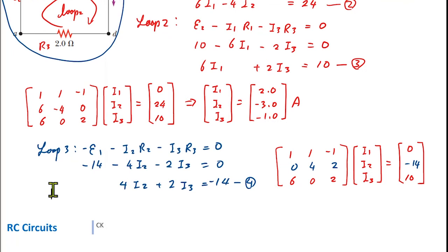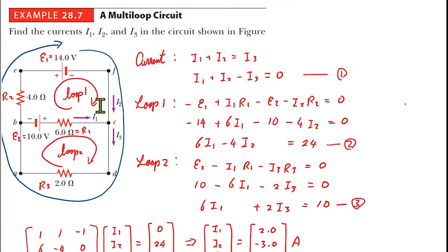So when you draw these loops, I will always try to draw everything in the same consistent direction, but do it in a way to only put one battery in it. That way, it's a lot less confusing. You don't have to think about it a whole lot. Sometimes it requires 3 different loops, then you have a 4x4 system of equations. But in this case, it worked out.